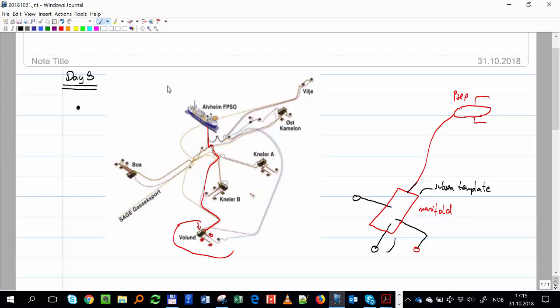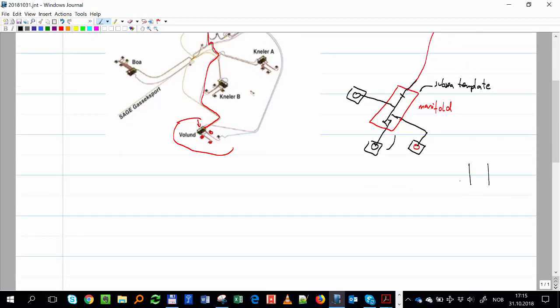If I wake you up in the middle of the night, you have to tell me, how do I commingle production from many wells? I use a header, right? The header, cabezal. So I have a header, and the header is connected to that pipeline, and I have all these wells coming to that header. The way it looks, usually this well is by itself. When you see it from the side, you have the seabed, and then you have the well, and then you have a big box, which is the Christmas tree.